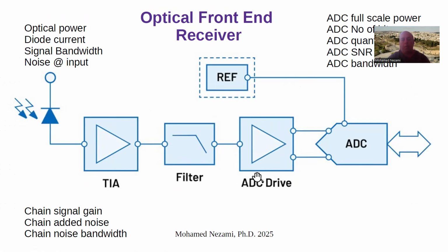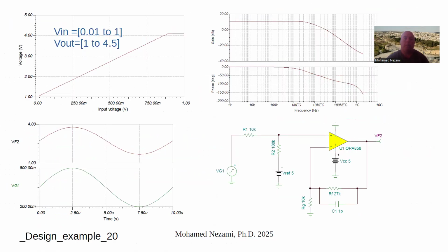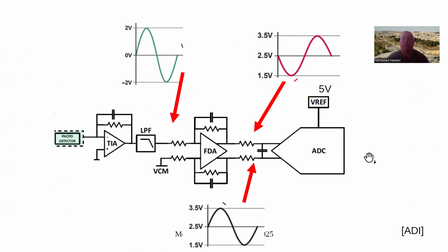But we have seen how you manipulate the DC offset and the gain and the slope or the polarity of this stage in here. Now, this could be, of course, single-ended or differential. In a lot of cases, we're dealing nowadays with differential amplifiers driving ADCs. If that's the case, nothing changes. Everything I talked about for single-ended still applies, but you have to do it with the fact that you have a differential amplifier.